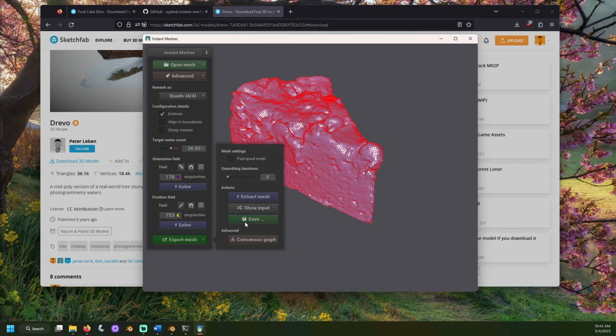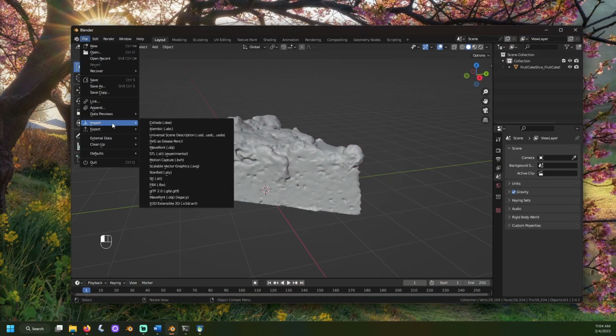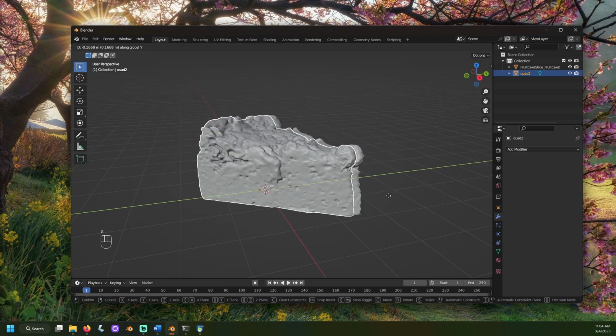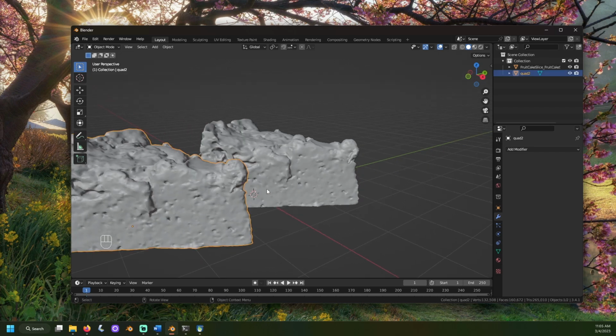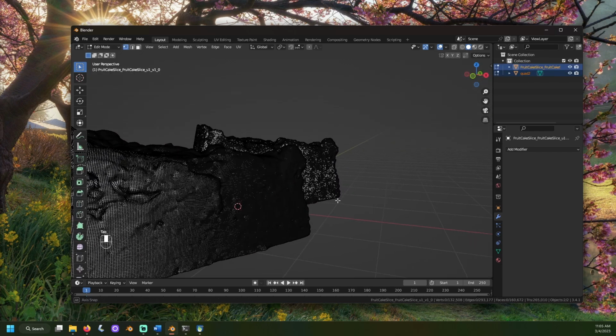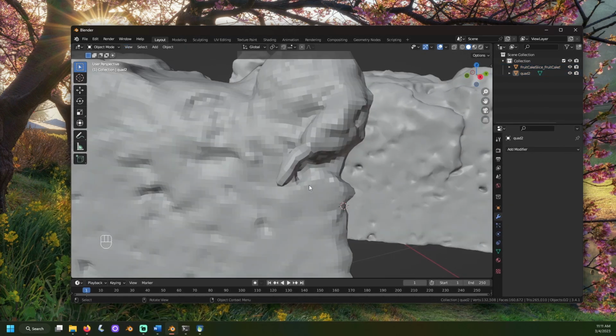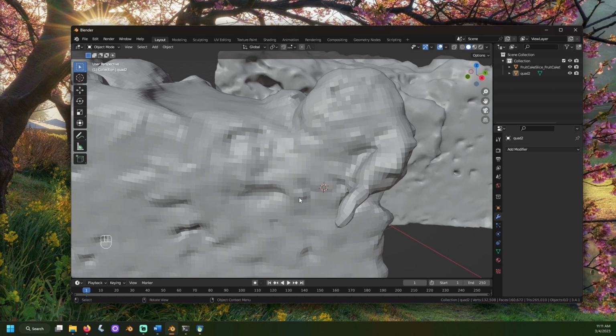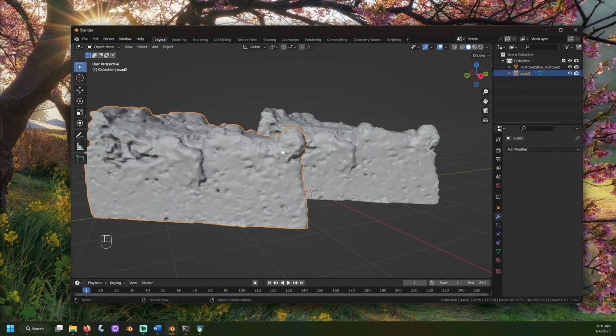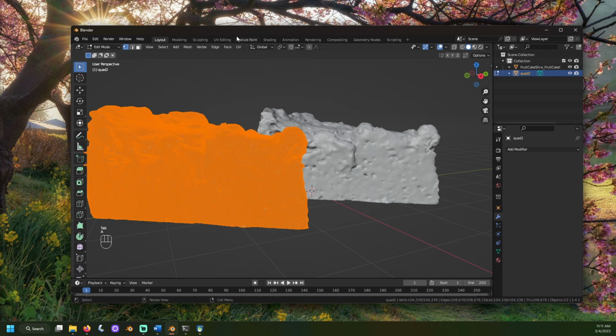Let's open our mesh back up in Blender and compare the layout to our original. I selected both meshes with Shift and opened in edit mode. We can see our quad mesh is a lot more evenly laid out, while our former mesh is a bit less organized. If you want the square look covering the mesh to change, an option you could take is to open edit mode, press A to select all, click on face and shade smooth.